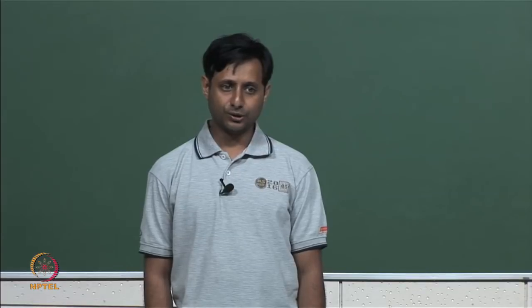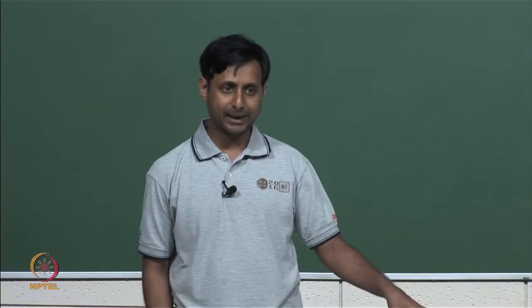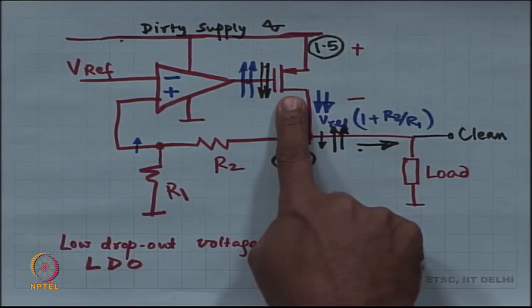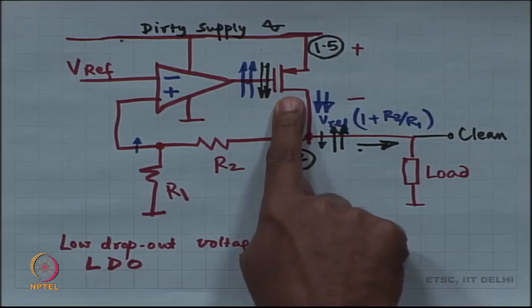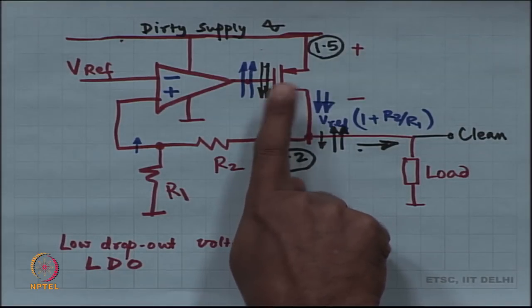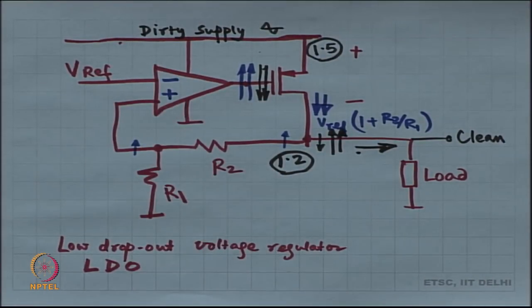and this is going to perform much more efficiently than the classical voltage regulator, right. The classical voltage regulator is the standard feedback amplifier. This one has an extra inverting amplifier. Okay. Instead of a buffer, a common drain buffer, you have made a common source amplifier over here. That led to, of course, a flipping in terms of sign, but otherwise everything is the same. Fine. Any questions so far?